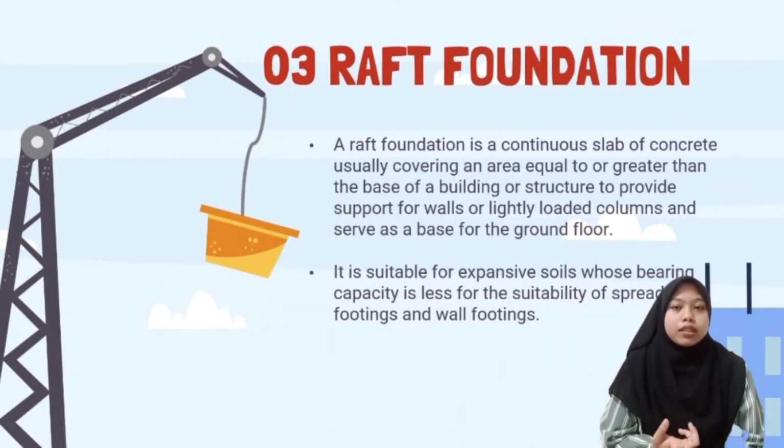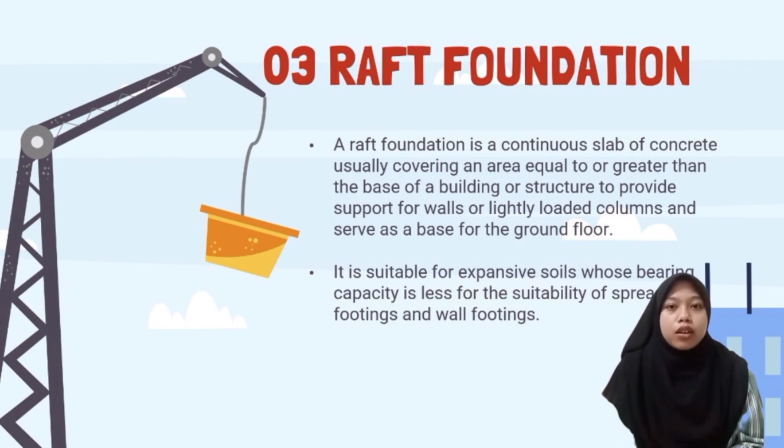Third, raft foundation. A raft foundation is a continuous slab of concrete, usually covering an area equal to or greater than the base of a building or structure to provide support for walls or lightly loaded columns, and it serves as a base for the ground floor. It is suitable for expansive soil whose bearing capacity is less for the suitably spread footing and wall footings.